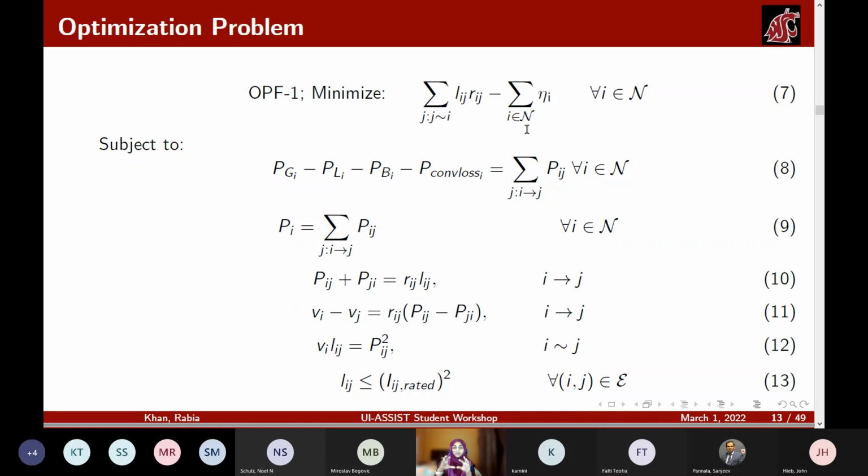We will be considering multiple nanogrids in the system, assuming a nanogrid to be like the ith nanogrid. Each nanogrid has its own index i, and each nanogrid can operate independently as a source, and it has its own load and its own battery, and we assume at the moment that we have one converter inside the nanogrid that will be operating. The power injected at each output bus of the nanoconverter is equal to the summation of power flowing to the other buses or other nanogrids, and this is the same one that has been used, but we are going to change this equation.